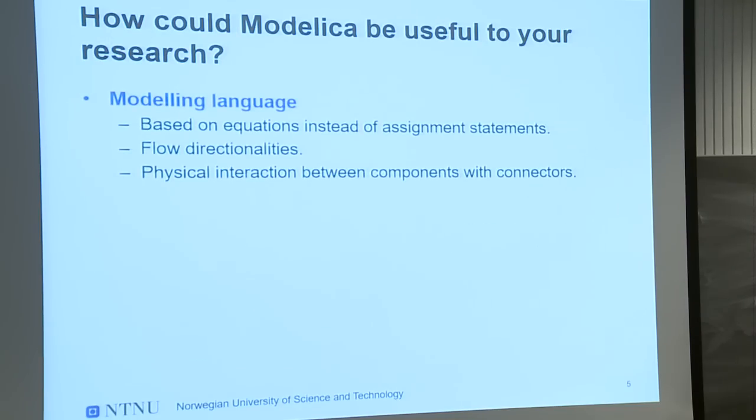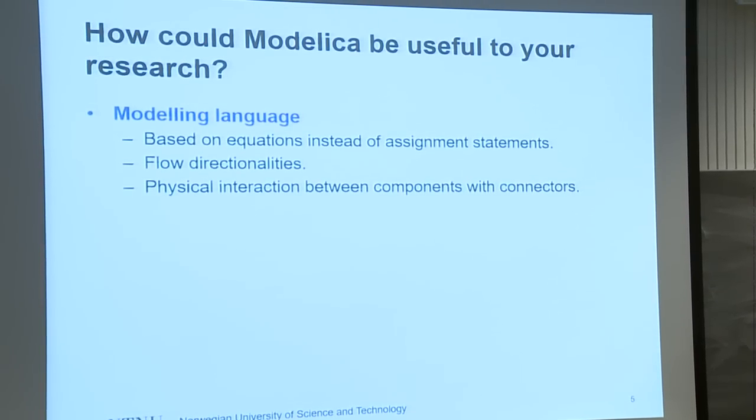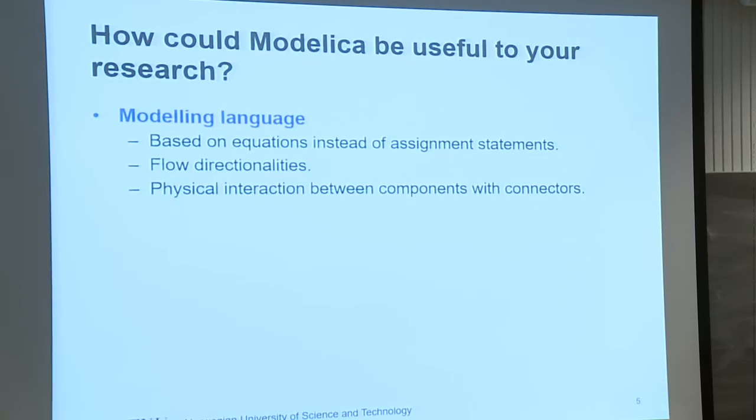So, coming again, why should you use Modelica? The advantage of Modelica is you don't have an assignment statement. Everything is based in equations. So the left side of an equation does not have to consist of only one variable. You can have an equation which is complicated to solve for one variable. You just write it in the complicated form. You don't have to solve a quadratic or any other polynomial equation for a variable. You just write it the way you have it, and Modelica gets it for itself.